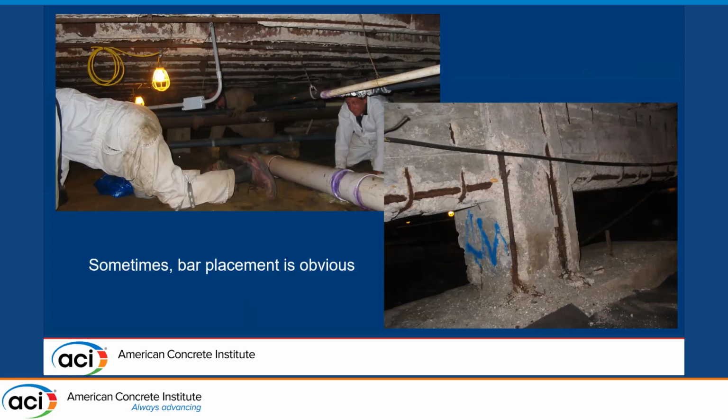The advantage here is that in this crawl space, we were also able to see the top of the foundation, and we got down the sides and saw what kind of foundation system it was. Yes, you need the foundation system because in this case, we're in a fairly high seismic zone. The seismic loads were much larger than they were ever designed for. In fact, it was almost not designed for any seismic load. And so you need to know what's going on down there, right? Okay.